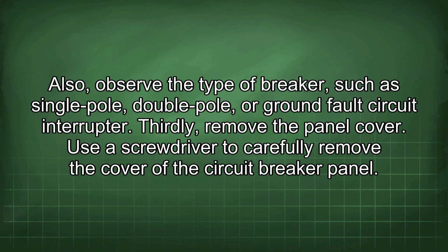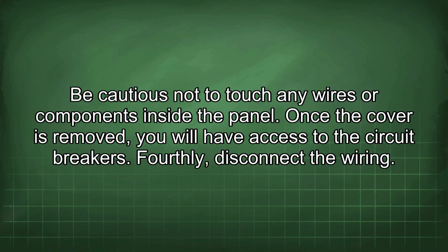Thirdly, remove the panel cover. Use a screwdriver to carefully remove the cover of the circuit breaker panel. Be cautious not to touch any wires or components inside the panel. Once the cover is removed, you will have access to the circuit breakers.